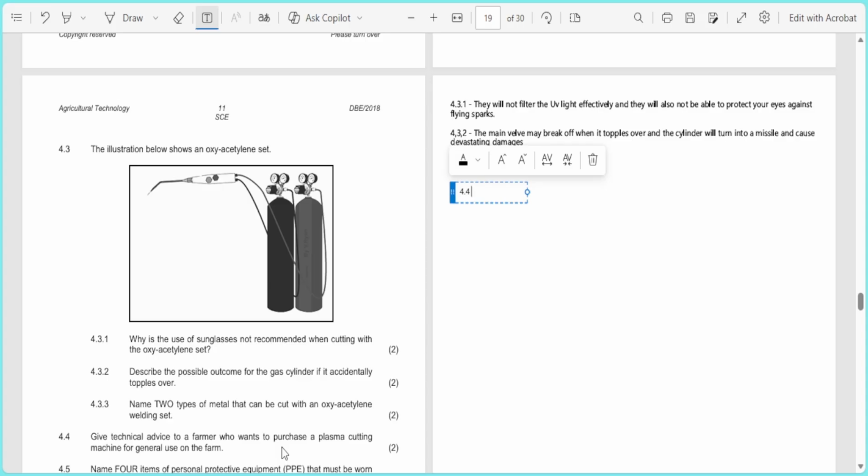So the compressor is often overlooked. Plasma cutting needs clean, dry air at constant pressure. So a cheap machine might save money up front but cost more in downtime and consumables. So for farm use where reliability is key, quality is going to matter here, right? So the farmer needs advice. I would say buy a machine according to the thickness of the metal to be cut. Number one, the thickness of the metals you are normally working with on a daily basis, right?